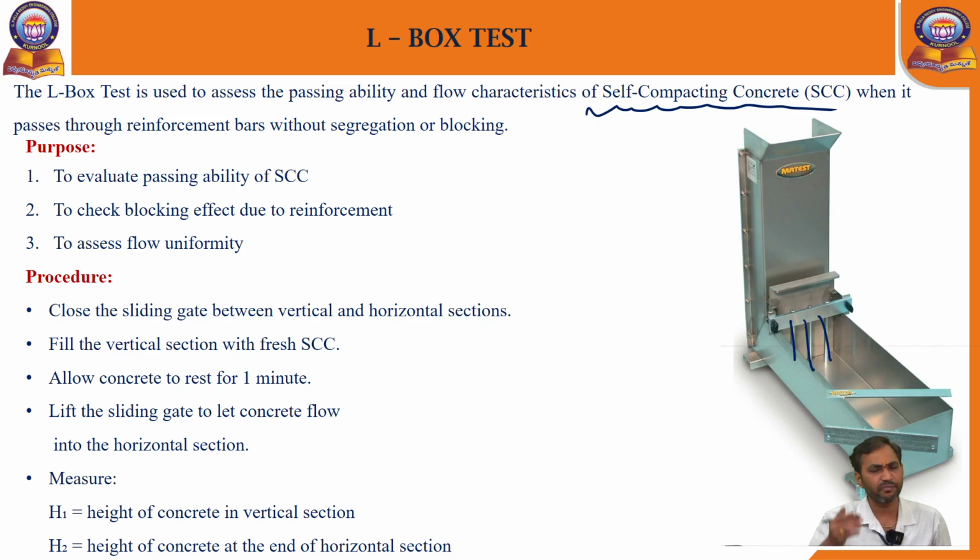For every type of test, there is a different nature. For the slump cone test, good workability and quality. For the Kelly ball test, workable nature and also quality. For the compaction factor test, what is the placing nature? For the flow table, what is the flowability nature? And the VB consistometer, the time taken for vibration, only for stiff concrete. Like that, for the L-box test, how the concrete flows properly in between the reinforcement steel bars.